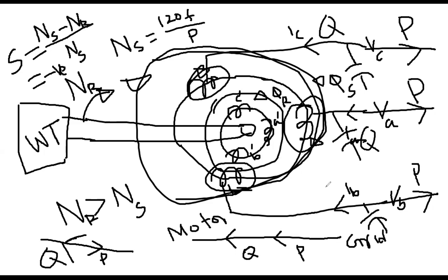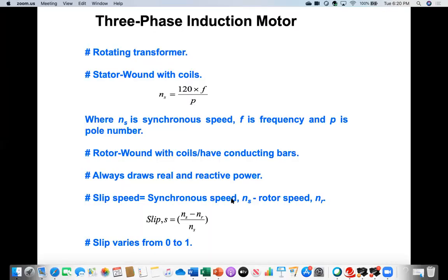So that thing you told, because without the capacitor, it is always drawing reactive power. This means it is providing low lagging power factor. And what is the consequence? There will be a voltage drop, but you have to maintain a steady voltage at the terminal. Therefore, to compensate the low lagging power factor, in other words, to maintain a steady voltage and to improve the power factor, we have to put a capacitor at the terminal. That will be the answer. Okay, I think everybody is fine. Now move to the other two components.